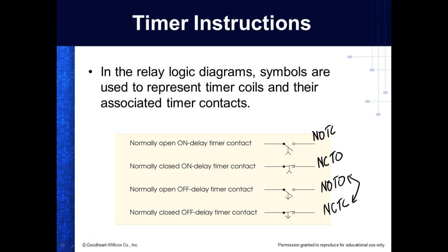So that means this guy's going to close instantly, right? You understand that? And then when you turn the timer off, it's going to do what? It's going to time open, right? Does that make sense? So this is the way these guys are going to be nomenclatured or named. Normally open, timed, and so notice your on delay timer, they're opposite. Your off delay timer, they're what? The same. You understand what I'm saying?